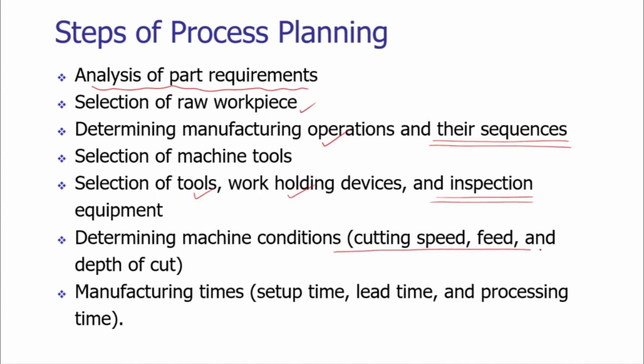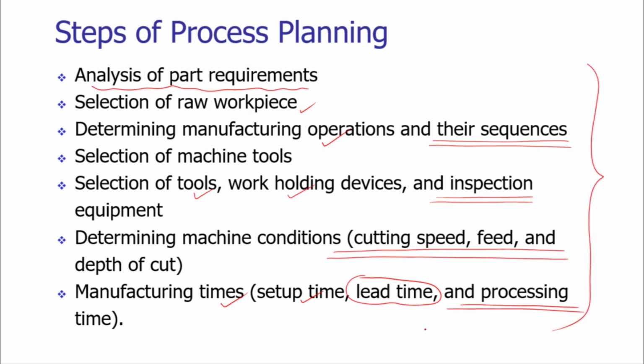In addition to that, the technical details regarding the cutting speed, feed, depth of cut, the setup time, the estimation of the setup time, estimation of the lead time, that is the preparation time, and the actual process time. So recording of the same, monitoring of these times, and based on that, avoiding the bottlenecking. So all these things would be done by the process planning in a stepwise manner, in a phase-wise manner.